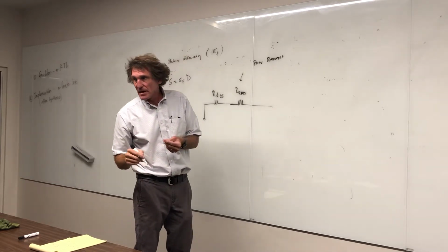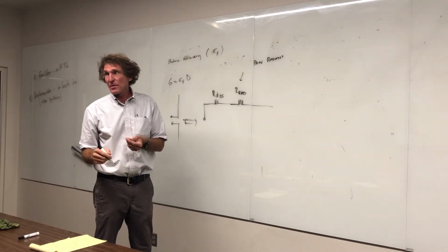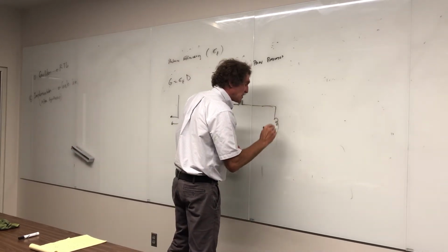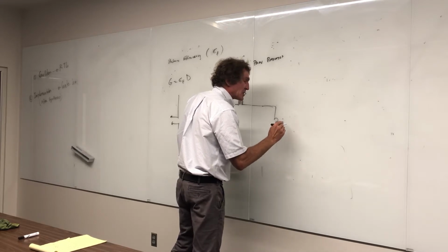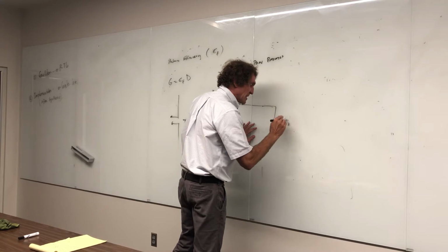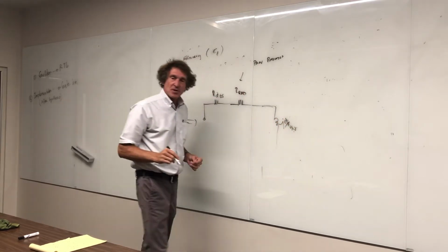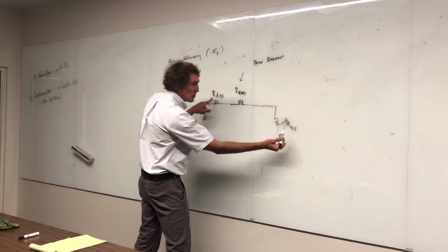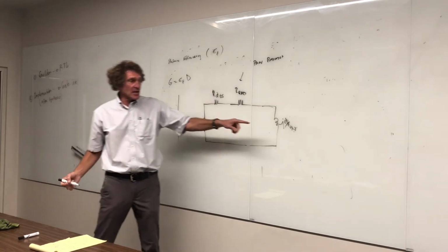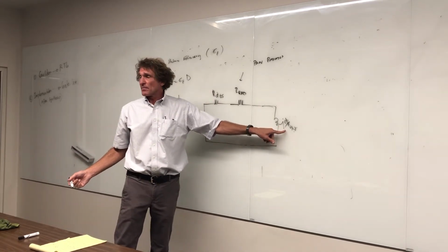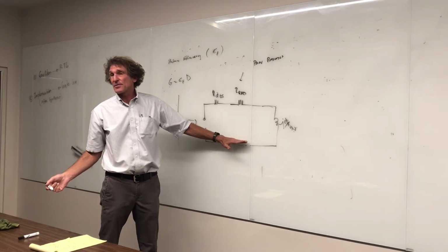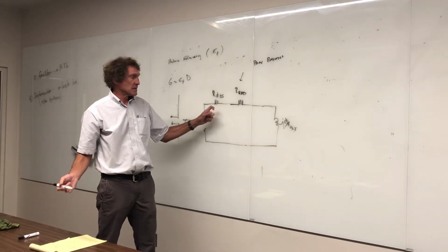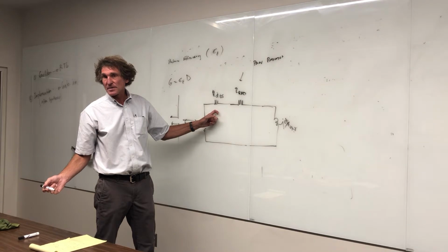But with an antenna, it's not always going to act the way you want it to. A lot of times it has an antenna impedance, either a plus or minus J, and you can just call this Z, or call it X antenna. It could be a minus J, which would be a capacitor, but this is not wanted. You don't want dissipation, you don't want that JX. Now this JX, say if it was J70 ohms here, that's easy to get rid of. Just put in series with this a capacitor that has minus J70, right? Then the total would cancel. You follow me? But you can't get rid of the dissipation. That's there. You've got to live with it, and that's something you don't want.